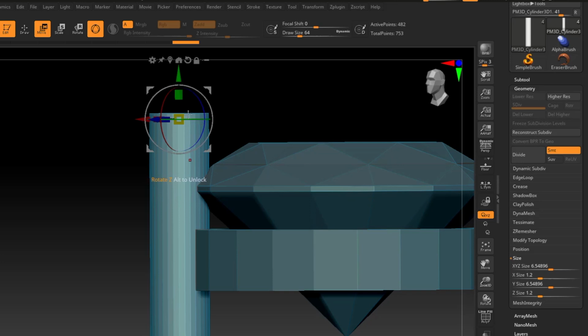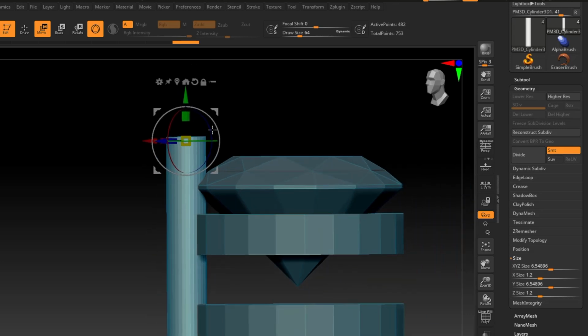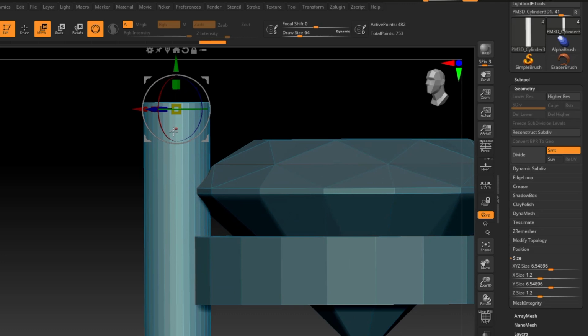It's better to have too much prong on top than too little, because the person setting it after it's cast will always be able to remove metal, but putting it back is much more difficult. So don't be afraid to have a bit of extra metal on top, and that will allow the setter to have plenty of prong to bend over. The ends of these prongs will get shaped after it's set, so some of that metal will be removed.